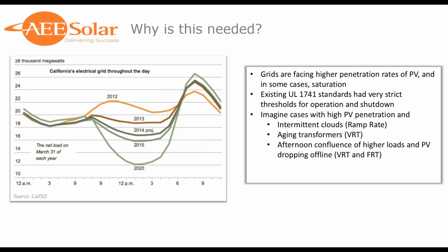You've also got issues when cloud cover passes, or, say, an August 21st total solar eclipse. You're having these inverters come offline. 2 minutes later, the clouds or the eclipse passes, and the inverters are going to rush back to full power output. And grid operators have to be prepared for that to happen. The only things that the grid operators can do is use things like combustion cycle turbines and capacitor banks, et cetera, to support the grid.